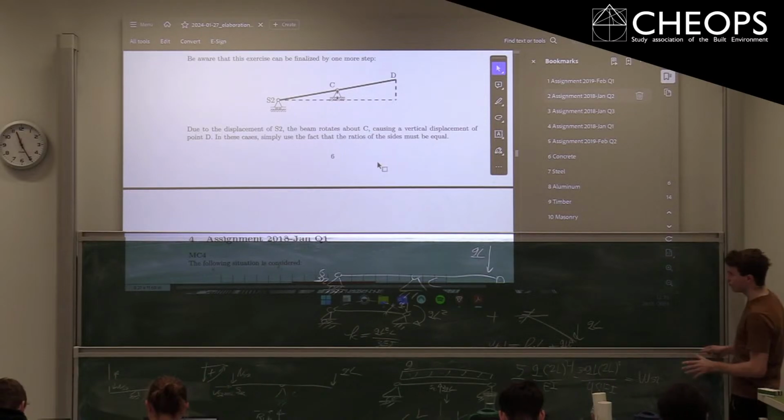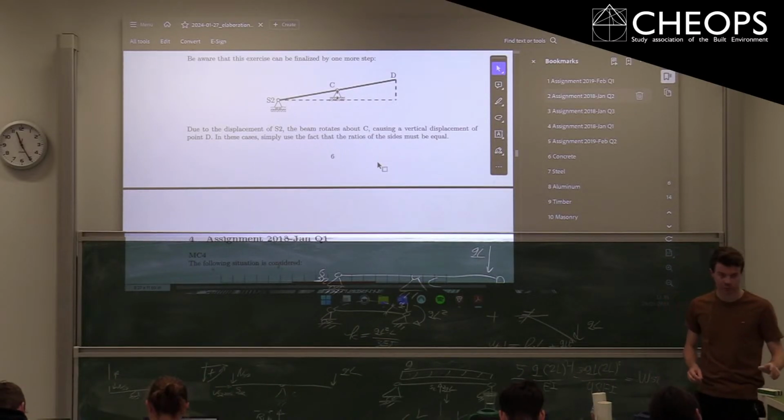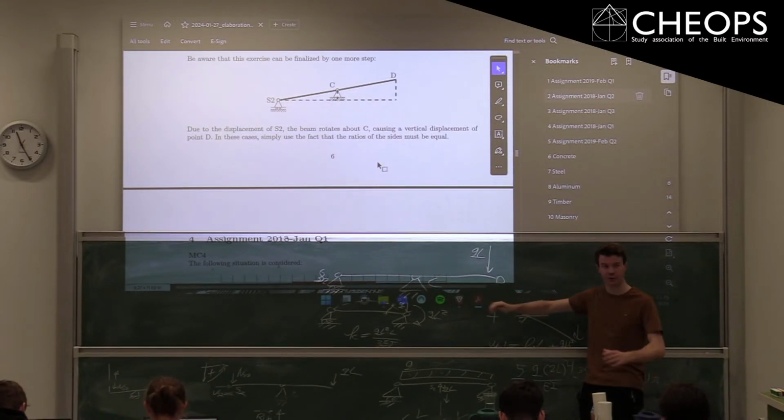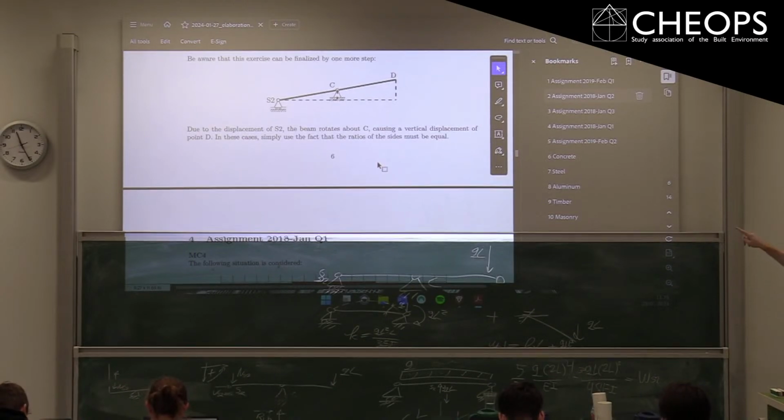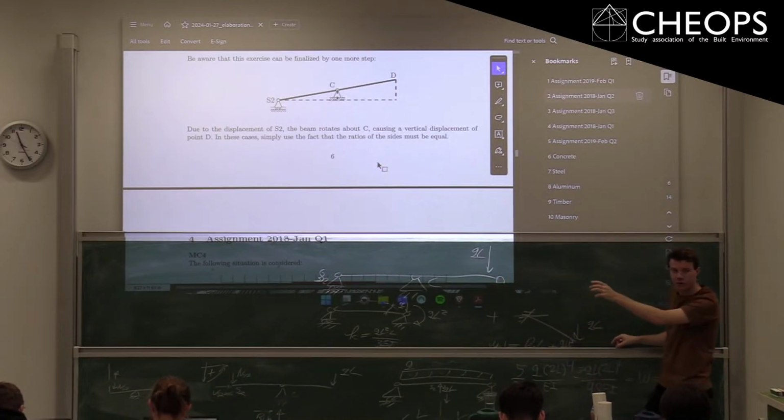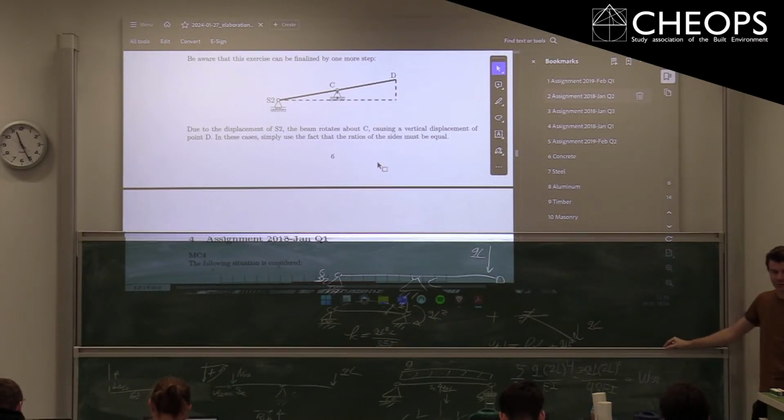So it's a good question. Nothing, actually, because this part stays the same. So you split it actually in two. So that point C moves downwards, and that displacement of D that it causes is what you see there. But we also have the bending and so on of this beam due to QL, which is simply a different case. And because we're working with linear elastic structures, that means we can use superposition. We just split the cases and we add them back together.